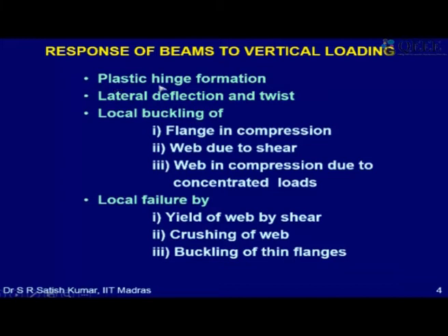We assume that it will eventually fail by plastic hinge formation, right? So even in elastic analysis, we may assume that it will at least reach the first yield moment. That is, the extreme fibers may reach My, but then in reality, before that, lateral deflection and twist may occur, right? Lateral buckling may occur. Okay, so that's something which we have to understand.